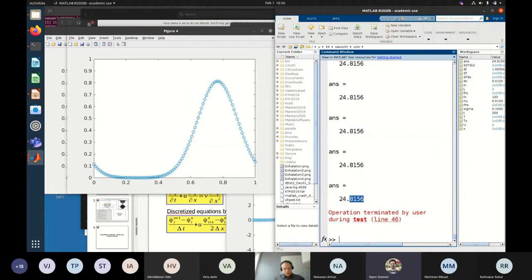Well, I had a question. If, for example, in this case, we are considering the temperature, how could this conservation be interpreted? In terms of concentration of particles, I can understand it, but how about the temperature? Then it would be thermal energy. So basically you have specific heat times temperature, and then you multiply with density, and if you assume density is constant, then that would be conservation of thermal energy. Okay, yeah, thanks.